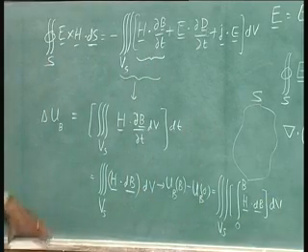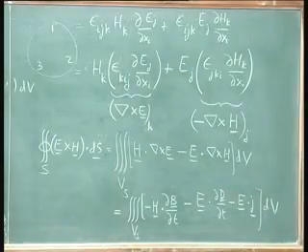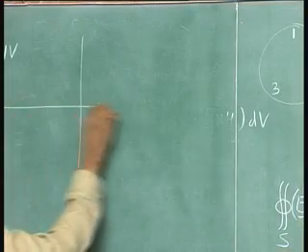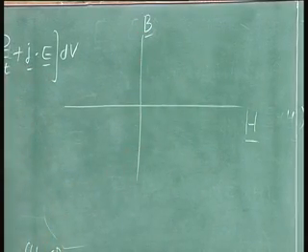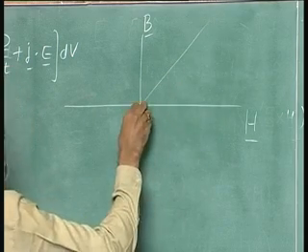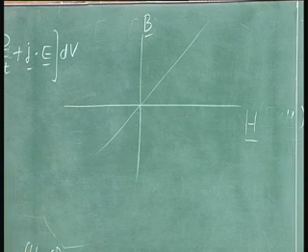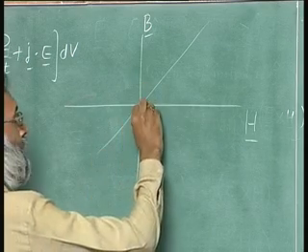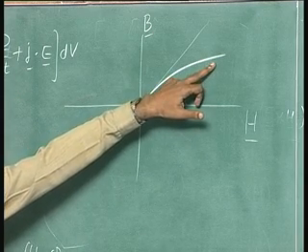Now, this should be familiar to you because as electrical engineers you have been working with machines and magnetic materials. So, you know that if you are dealing with a magnetic system, there is something called hysteresis. You have your H and B axes. If it were a linear system, you ought to have a straight line, B equals mu H, but that does not happen. In fact, if you take an unmagnetized material and apply a magnetic field, the curve that you see is very nonlinear, it saturates.